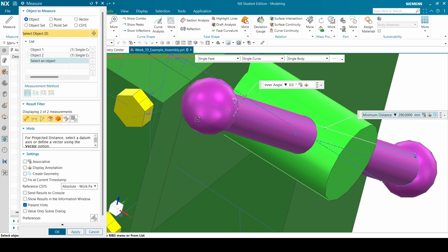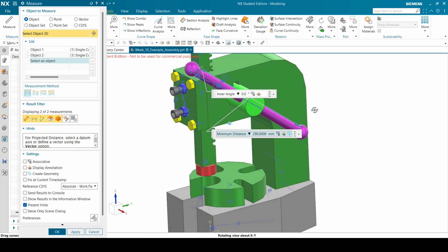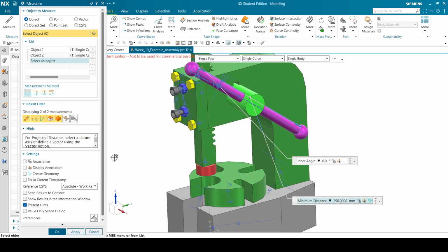And then I also saw many of you typing things into your calculators during the tests. Remember, NX can do math. So type in whatever you want your distance to be. If it's an equation, just type it into the box and it will calculate it itself. So there can't come any human errors in there. Well, there is less opportunity for human errors. Let's put it that way. So that is copied now.